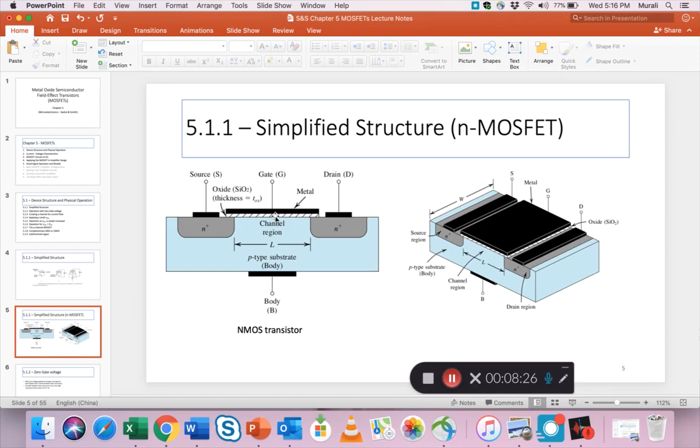And so what you see here is that the insulator is created using silicon dioxide. Okay, so that silicon dioxide is sitting on a big wafer of p-type semiconductor material. And the gate G is actually that conductor. So you have the conductor, you have the insulator, and you have the semiconducting material. Now, in addition to this p-type body, which also, by the way, has a terminal but is generally not too important in most applications, we just ignore it.